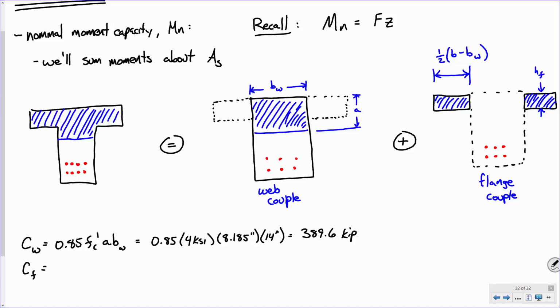flange force. Let's work that out. It's 0.85 f'c times what? Width times thickness times h sub f, right?